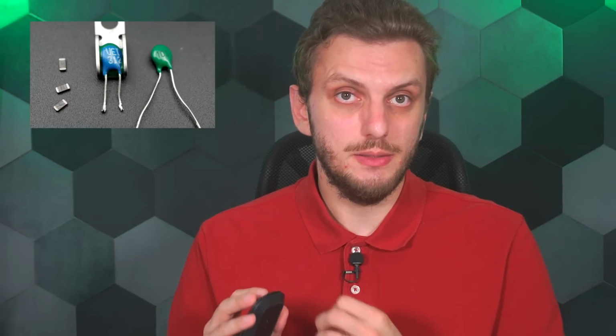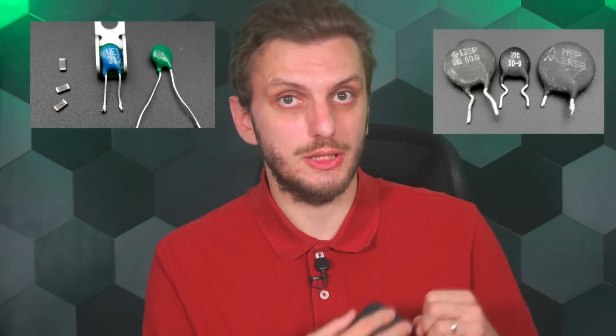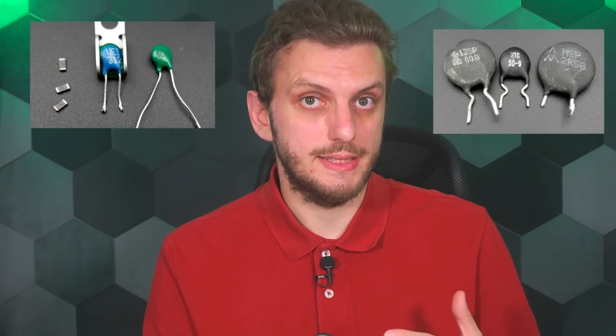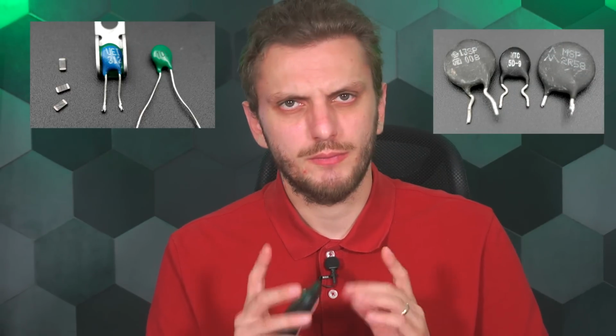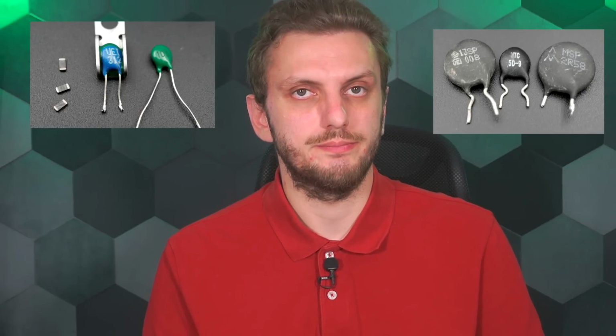Other than resistors, it's also common to use NTC type thermistors. Here, it's again important to mention that the same general problem exists. The thermistor needs to withstand the peak power that will get dissipated on it. So you have two big categories: the temperature measurement NTC, built for accuracy and small currents, and the inrush limiting NTC, which has an accent put on pulse handling. So make sure you choose the right type of component for your specific application.